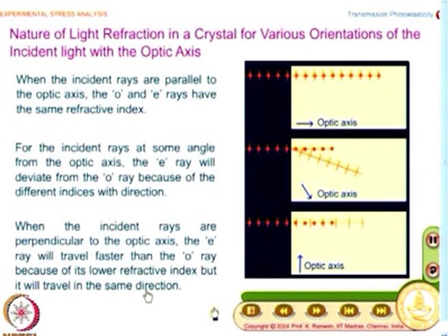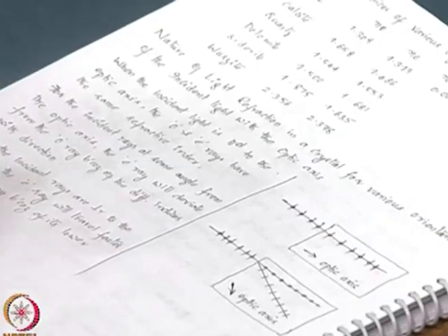This is very, very important, and you have already seen from a solid mechanics point of view, photoelasticity provides the difference in principal stresses. And I also mentioned in one of the earlier classes that refractive index is a tensor of rank 2, stress is also a tensor of rank 2. So, whatever happens to refractive index, I can match it on the stress tensor.